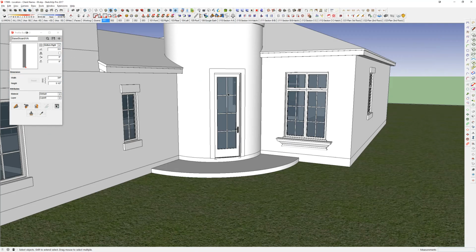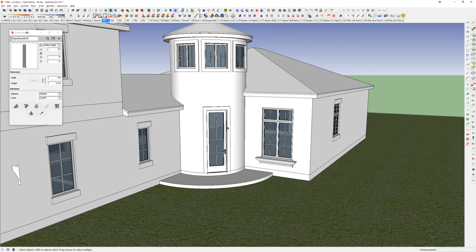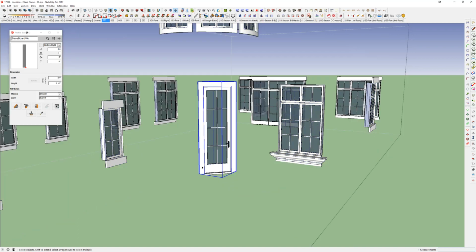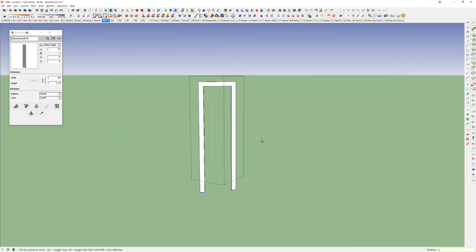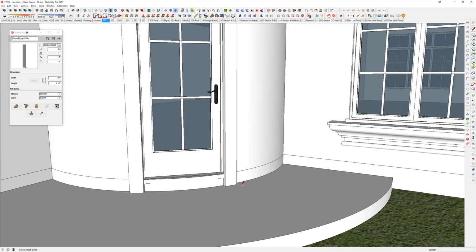There you go. So I hope that was a little bit of an easier way of explaining it. Doing trims around round towers can be a little bit more difficult. But in my mind, if you properly think about the steps of doing it, which I did not do initially, and just work through the idea and the tools that you have, you can eventually come up with something that'll work well, which I think we just did. I'm going to pull this down just so that my trim is hitting down here the way it would.